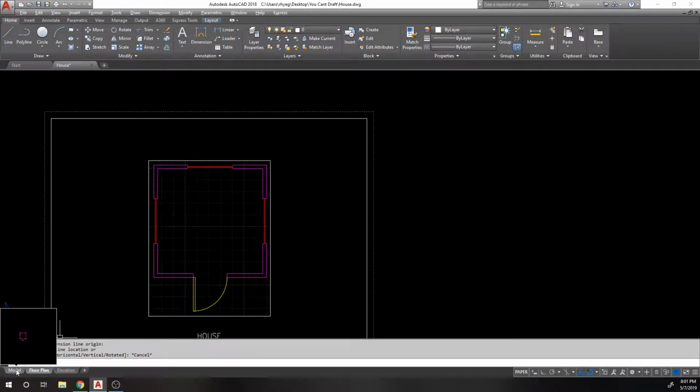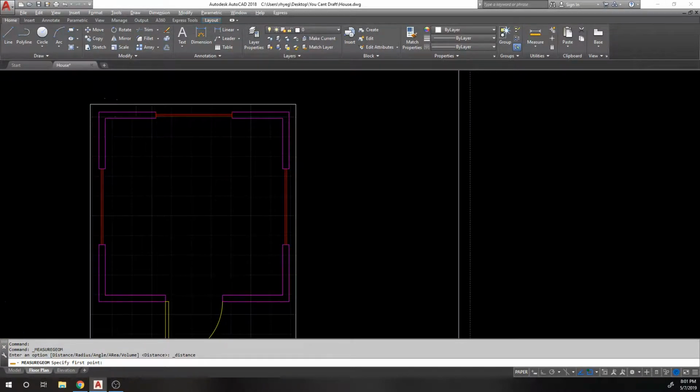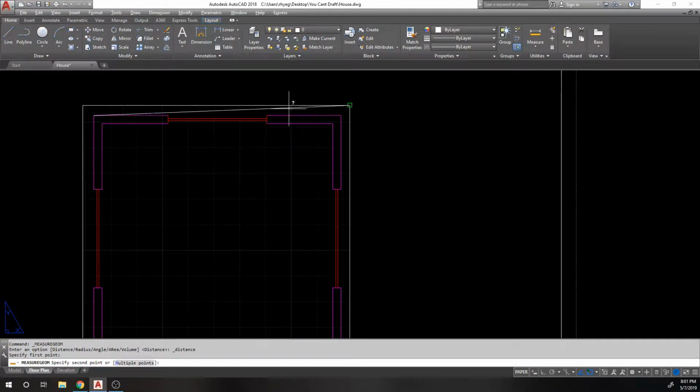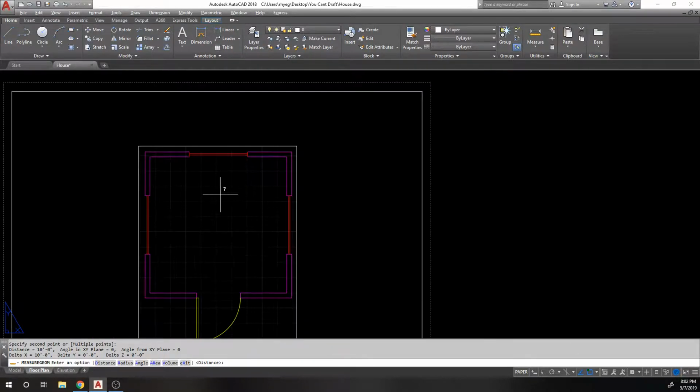If I were to go and measure that using a distance command, which you can measure without having to go inside the viewport, you can measure from here as long as you're measuring just model space objects. I click one point to the next and you can see my measurement says 10 feet. And yes, there are controls to modify the behavior of dimensions, because you'll see that it's returning 120 inches instead of saying 10 feet.